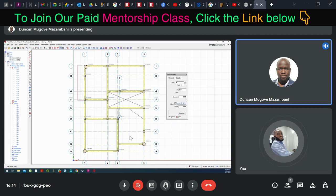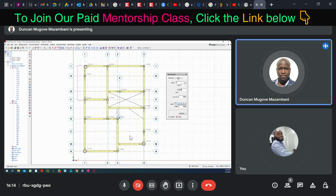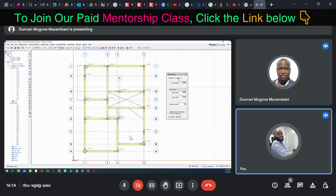Now click on loads. Concrete cover 25, yeah, cover is okay. On this load, you need to insert your dead load and your imposed load. Dead load comprises partition load, finish load and all that. I always advise to use 1.5.